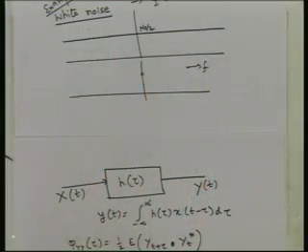And we have seen a particular example of a power density spectrum. It is a simple example, but a very important one because we will come across it in this course very often. That is the white noise. White noise is a particular process for which the autocorrelation function is a delta function. That is, the power density spectrum is flat.